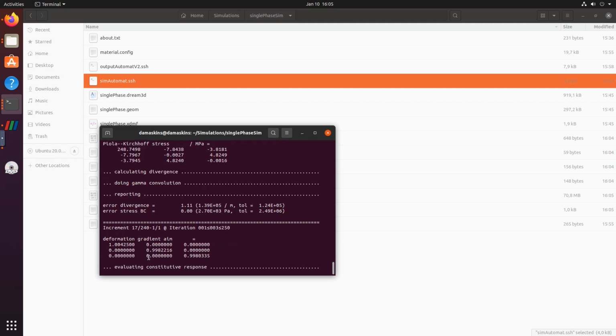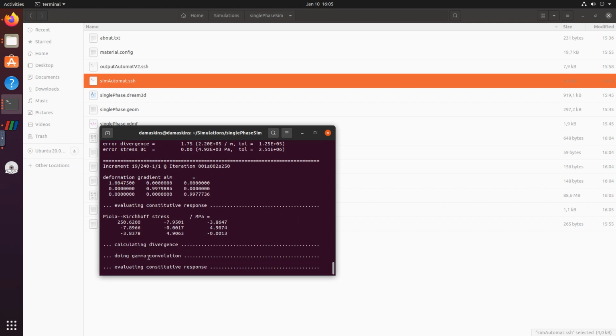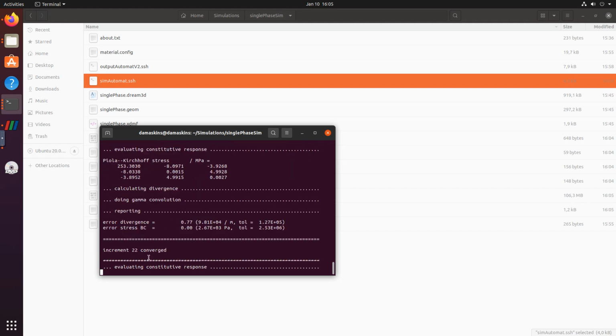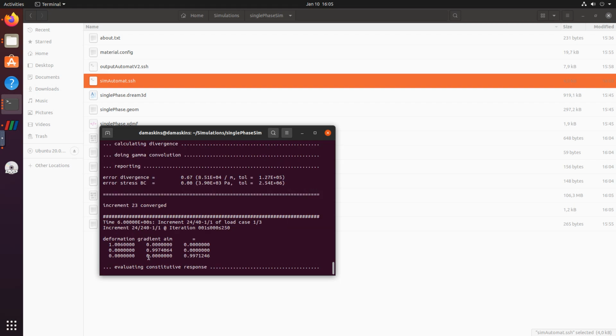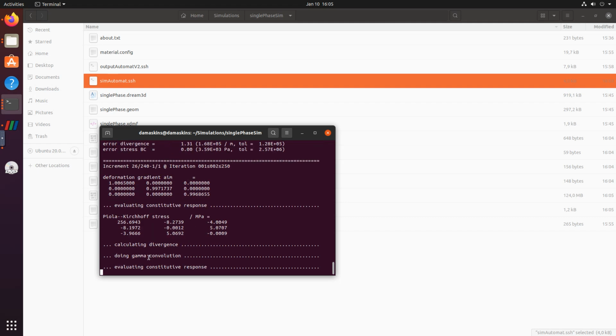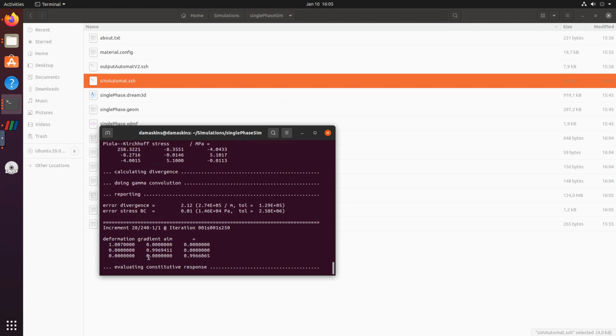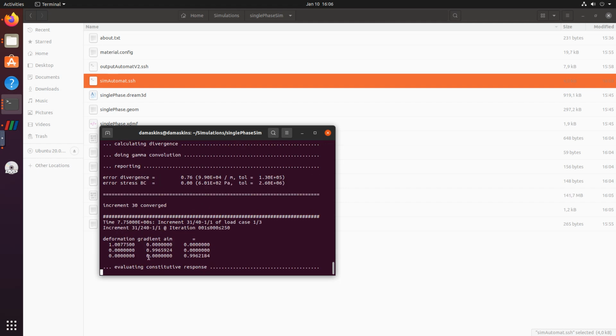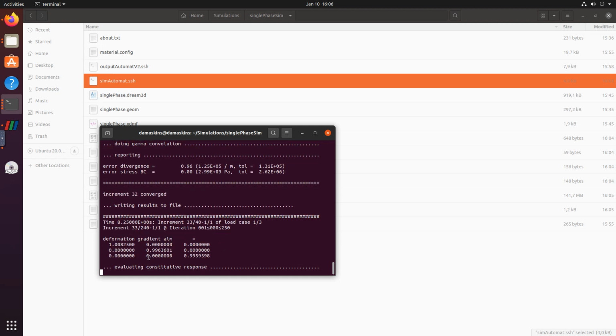You can also combine, for example, I've not done this here because I run fewer simulations, and I manually post process the results every time. But for example, you can also continue to write the script for ParaView visualizations. So you can import this file in ParaView, you can control everything, and you can directly export images in your folder from the ParaView visualization that you can just quickly see as JPEG files.